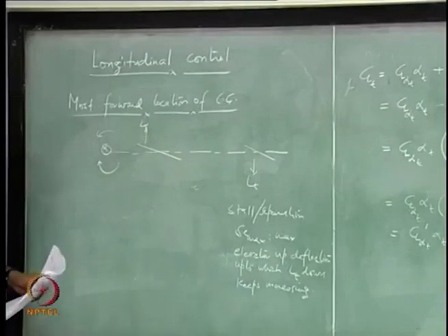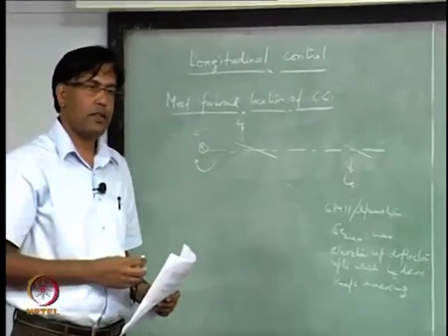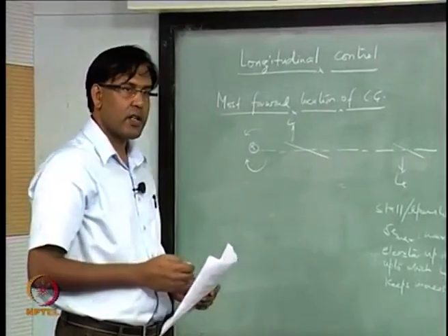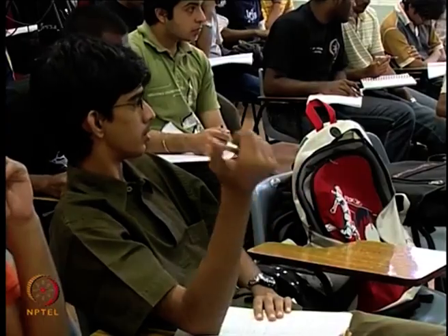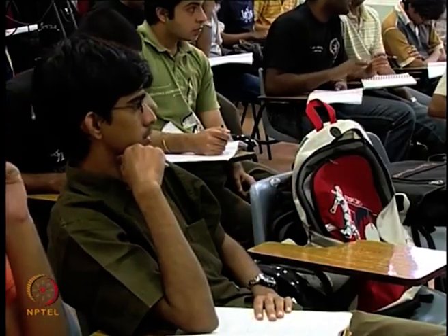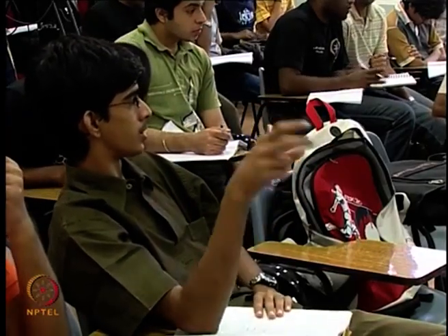So in this configuration, the wing has to produce an additional lift, right? The wing has to produce additional lift, because there is a component of lift downward by the tail, and we have to balance the weight. Yeah, you have to balance the weight. We have a stability versus wing load.